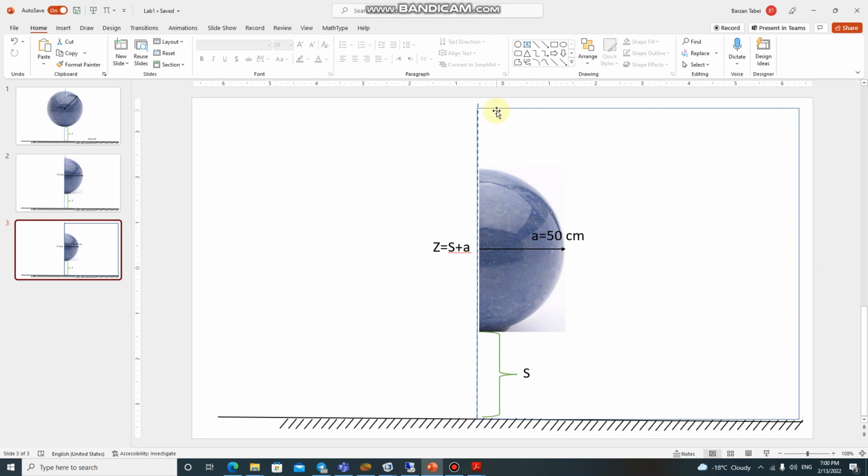You should know the dimension of this box. So in my calculation, I consider 5 meter as one side, but you should also consider 10 and 20 meters or whatever, and you should show the effect of increasing the dimension of this box on the convergence of the calculation and select a specific value.